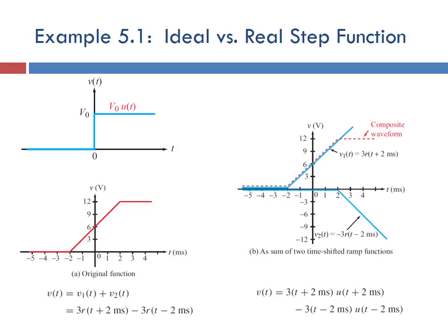And that's how you can take those two blue signals and pull them all the way back to picture A and make that original red signal. And the math is corresponding there too. You have two different signals, V1 and V2, and you're going to add them together to be VT, which is your red signal, your output. And the math is shown on how to do that based upon the 2 points.